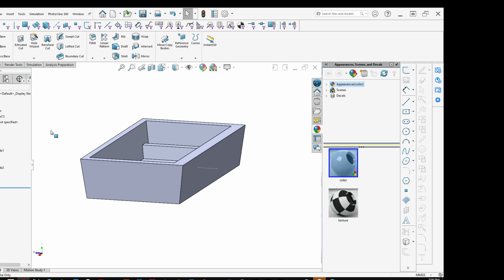So, injection molding, you can get down to a 0.05 wall thickness if you want. Most products go with 0.09. Higher quality products get up to 0.125, 0.15, and that's really the feel of the product too. You pick up a product and it just feels flimsy, it feels cheap, because they saved money on their plastic. You pick up a nicer, higher end product, so like you buy the $10 coffee maker versus the 30. The 30 feels a little heavier, the plastic feels a little harder. That's how you're going to determine it.